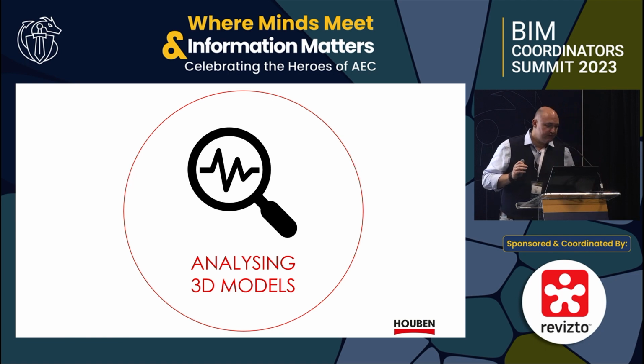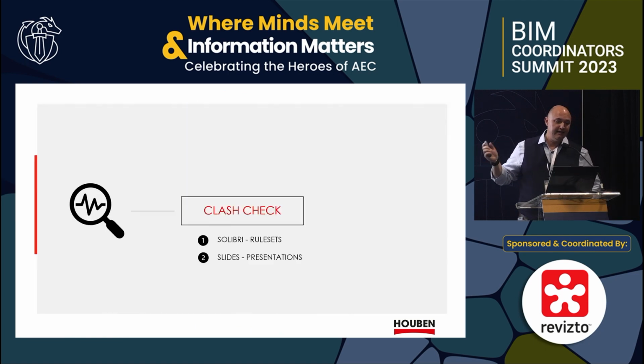The third one is something I'm going to get through very quickly: analyzing 3D models. What that means is clash detection. We also use Solibri with the rule sets to get the clashes, and we make slides for our presentation. The slides then have all the issues that we can communicate. So this is the third key task.